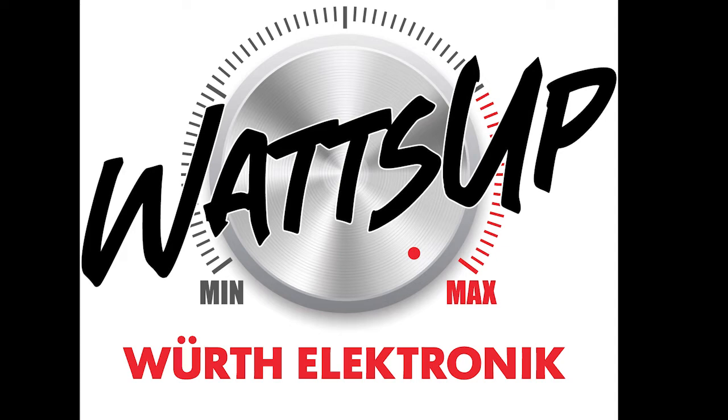Our second design tip is about the inductance value. The higher the inductance, the smaller the ripple current. The lower the inductance, the higher the ripple current. The ripple current is essential in determining the core losses. Besides the switching frequency, it is an important parameter for minimizing the power loss of the power inductor.